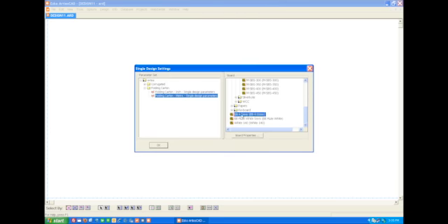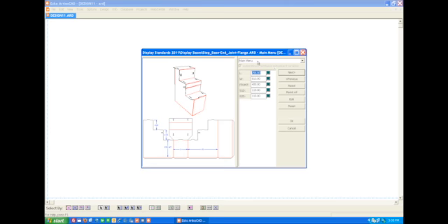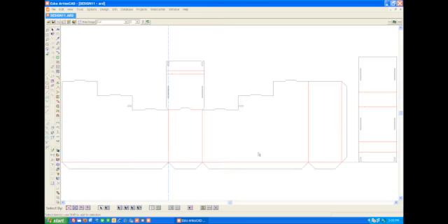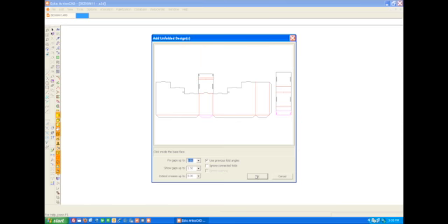Just to give you an idea, these are all standards where you can adapt new values and everything will fit into one another. So for this display, I'm going to start to make the base, and I'm going to, of course, add some board information. In this case, we are going to work with a non-folding corrugated EB flute, 4.5 millimeters thick. Here I can change my parameters. And if I agree on it, I have my structural design. In ArtiosCAD, by clicking on Convert to 3D, I will have the possibility to directly visualize my display in 3D mode.